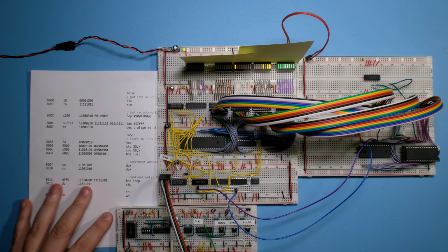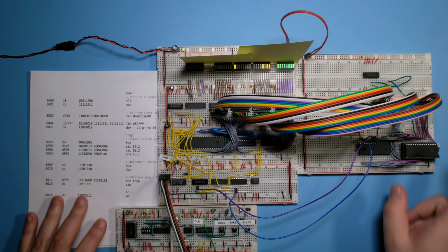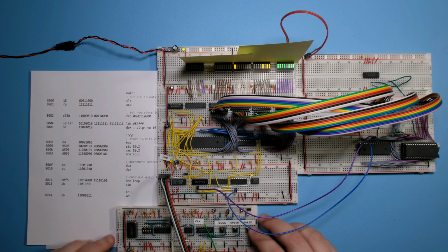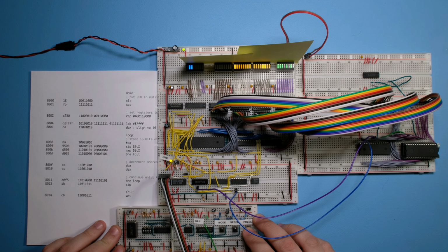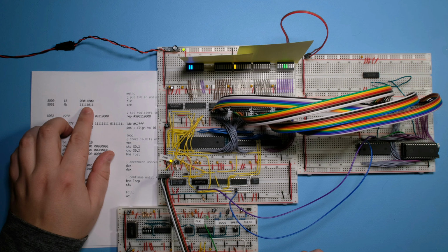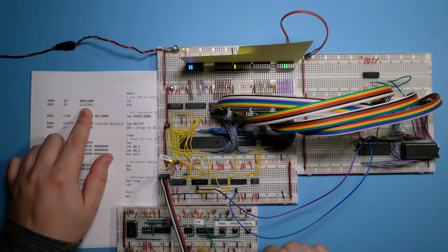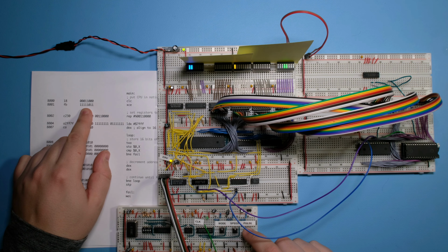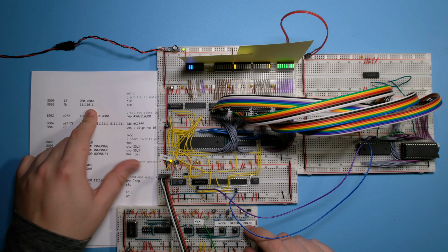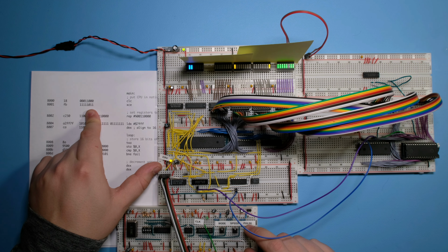So let me put this in place of the clock here so it's on camera. All right, so at the moment the CPU is reset. So let me load the first instruction. There we go. So the first instruction is CLC, clear carry. Then we are loading XCE, and so this is going to put the CPU into native mode. You'll see that the emulation LED will turn off. There we go.